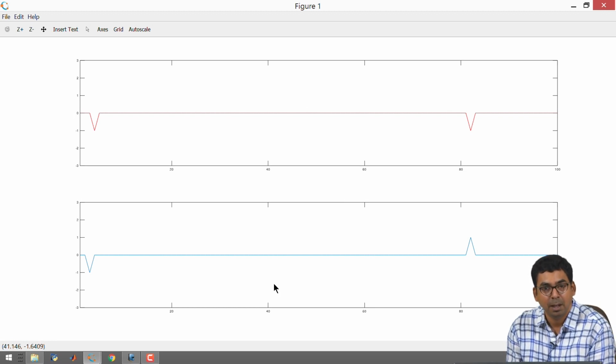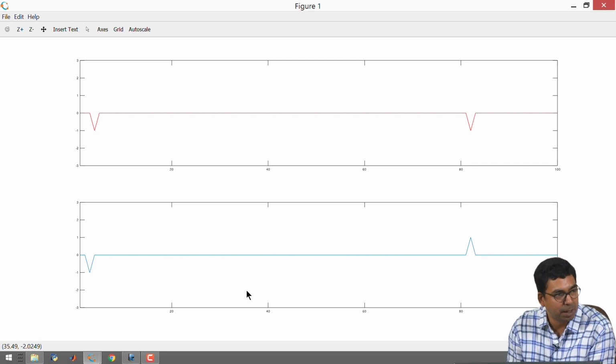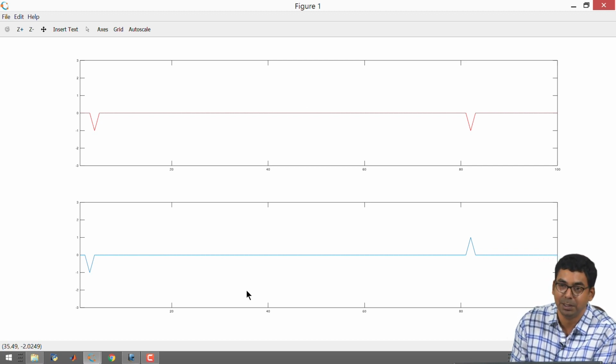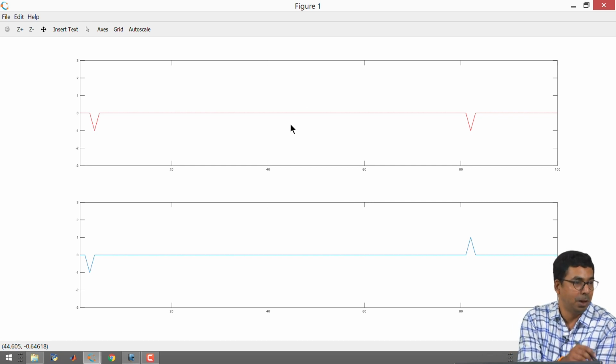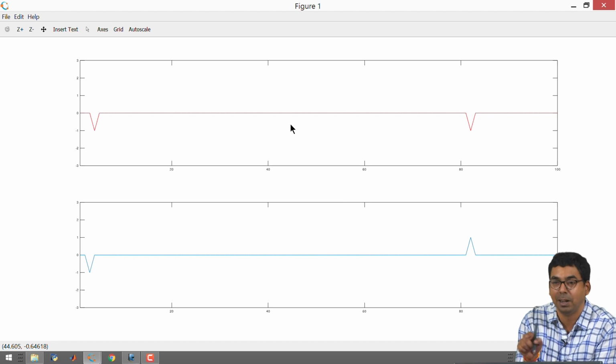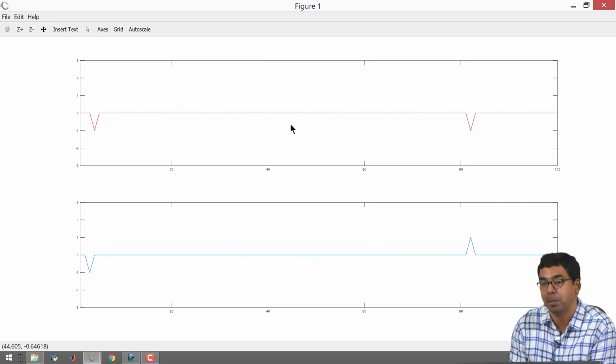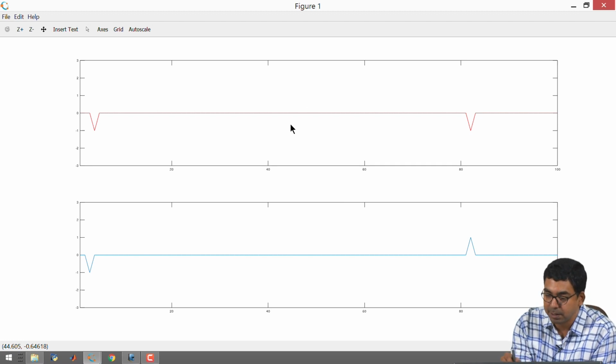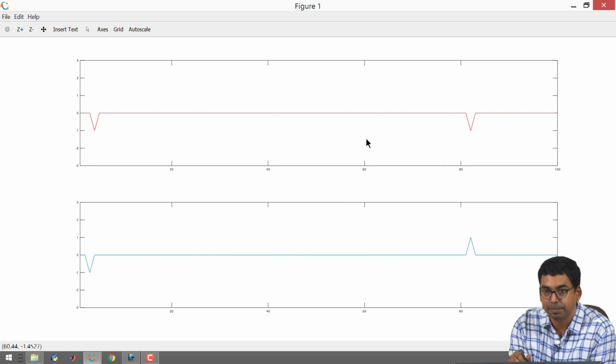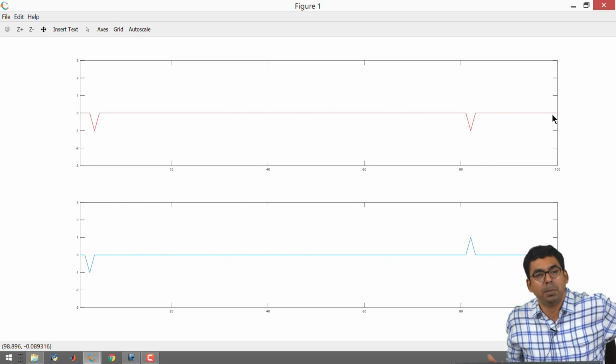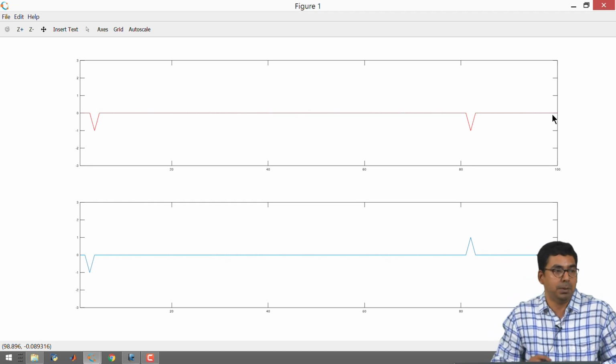Okay. Now this also has an impact on the way the current is going to be flipping back and forth, okay, and correspondingly one can calculate current reflection coefficients, but you can derive the current reflection coefficient from the voltage reflection coefficient, because you can apply your Ohm's law and also the sign changes for your forward and backward currents, and you will be able to figure out what's going on. So if one were to look at this transmission line section and try to derive information, we can always say that the right hand side was having maybe a short circuit or open circuit, I don't remember. On the left hand side it was the other case.